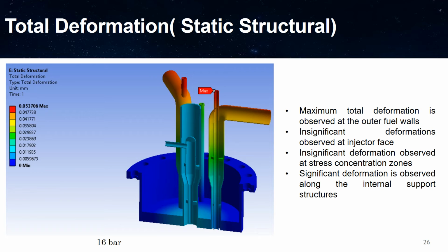But what worries me is that we can see the support structures going through a little bit of deformation. Since the support structures are very thin, we might want to reconsider how to design them, because if the internal support structures break, that means my fuel lines are going to be prone to catastrophic failure during operating conditions due to internal fuel pressure and external chamber pressure.